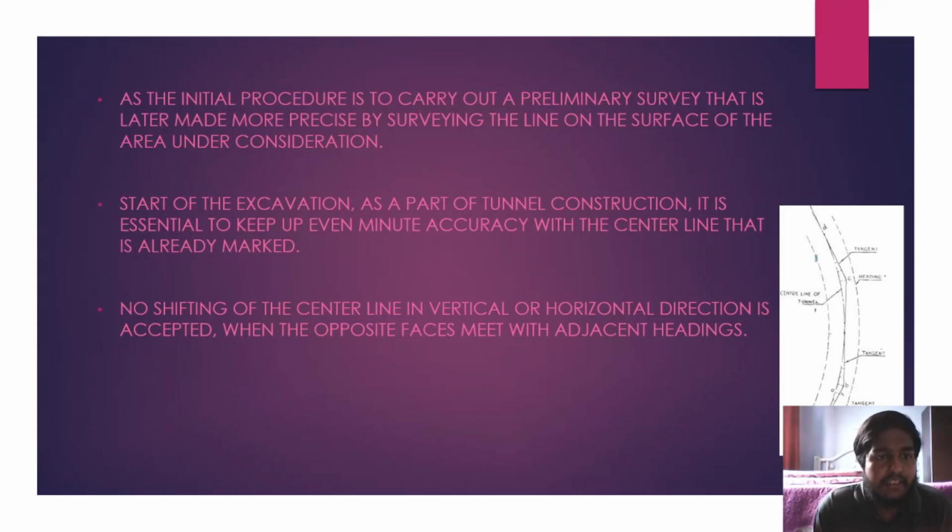When a new area excavation is commenced, the center line of the finished work has to be carried forward over the new phase. No shifting of the center line, in the vertical or horizontal direction, is accepted when the opposite faces meet with the adjacent headings.